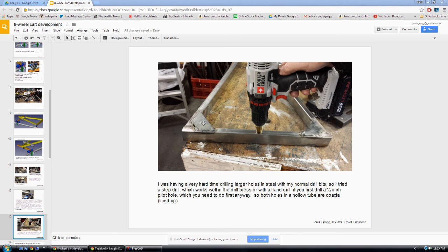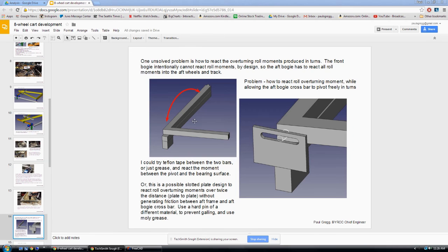Now, maybe there's a limit to how much welding you want to do, because weld wire costs a lot, and there's thermal distortion whenever you weld. But for what I'm doing right now, wherever I can avoid butt welds, I put a fillet weld, and I think it's turning out better from a design standpoint.